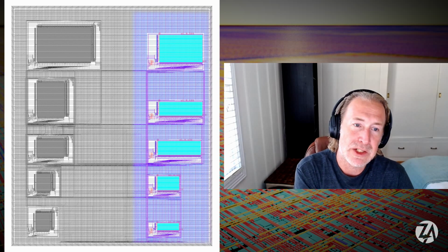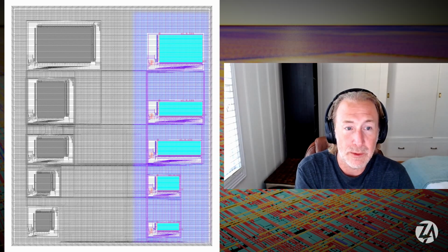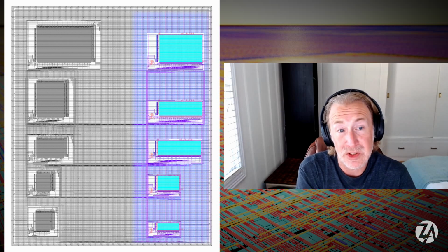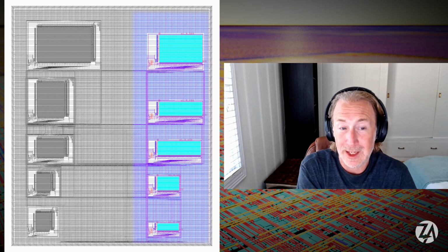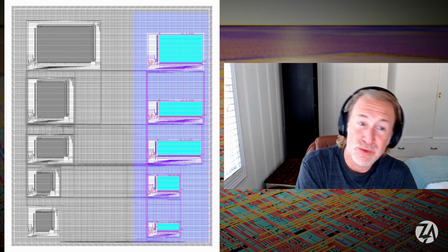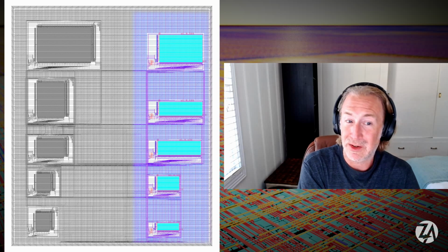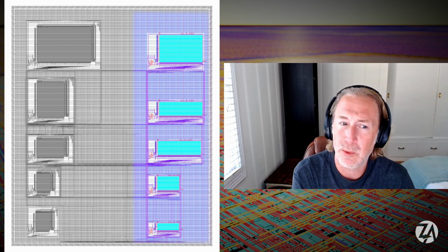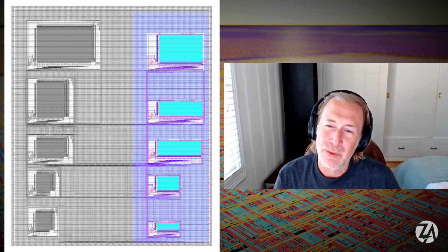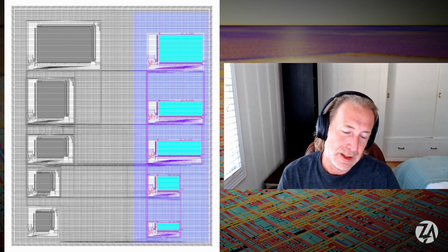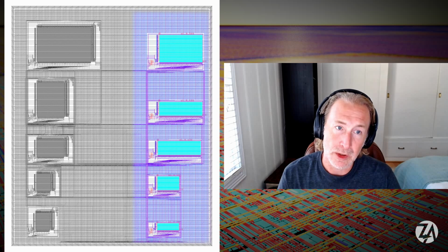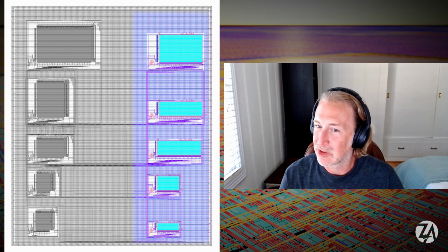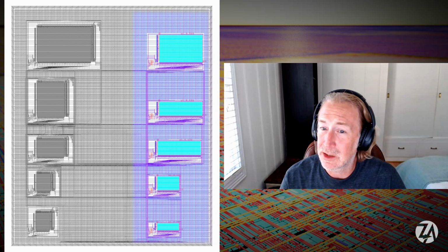And so we basically got the single port memories working, and we did five different sizes for that: 1 kilobyte, 2 kilobyte, 4 kilobyte, 8 kilobyte. And then there's two variants of the 4 kilobyte. One has a bigger, I guess the 4 and 8 have a 64-bit data word instead of a 32-bit data word. So you can see that the functionality varied not only by number of ports, but also by the sizes and the size of the data words as well. So that's kind of the variety of memories that we created.